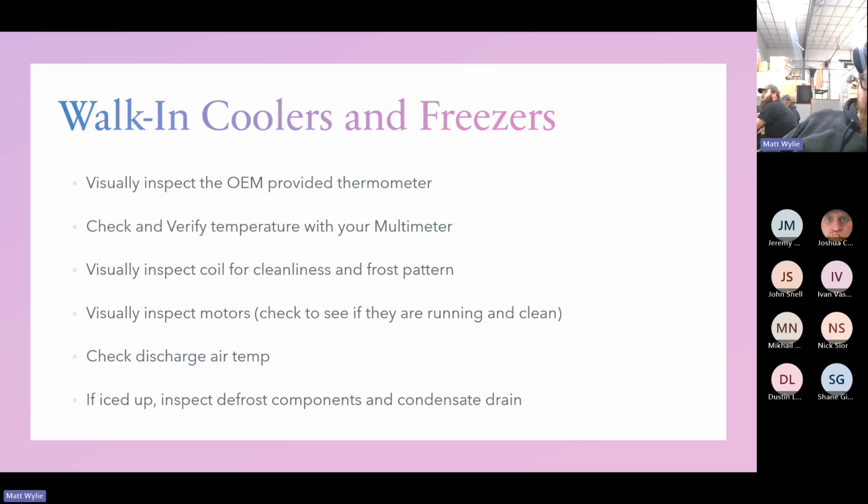Check discharge air temp. If iced up, inspect defrost components and condensate drain. So discharge air temp, your TD across the coil as well. If iced up and it's a walk-in cooler with a defrost clock, check your time.